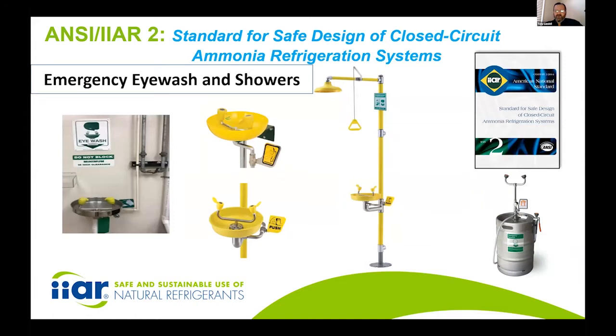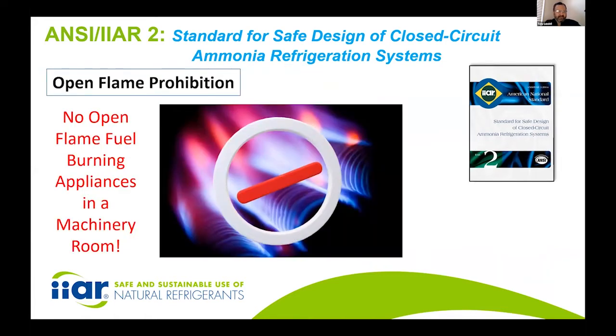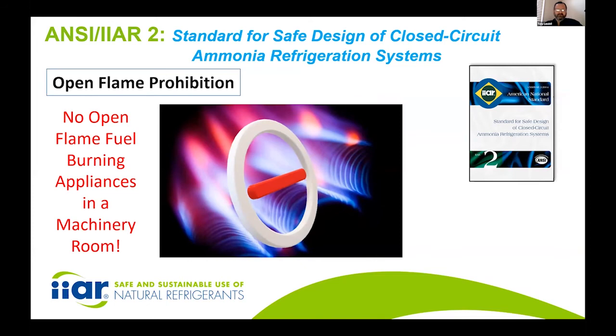And of course, emergency eye wash and showers are very important, that they're ready and usable whenever you would unfortunately need to use one. They should be ready, in good condition and cleaned. They can be portable, as shown in the one on the bottom right, but also wall mounted. You want to have signs, you want to have people trained to know where they're at, and of course they're checked frequently.